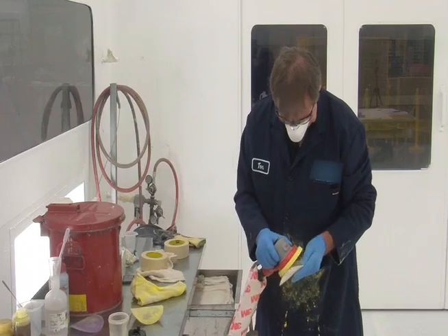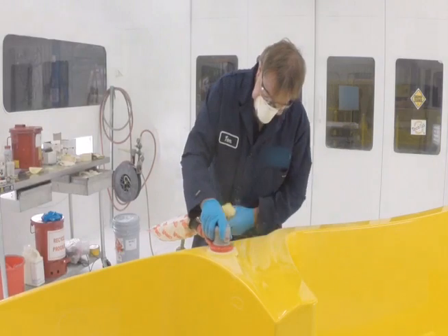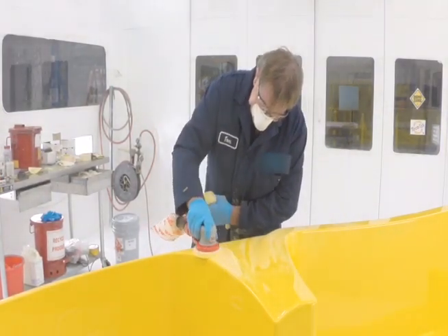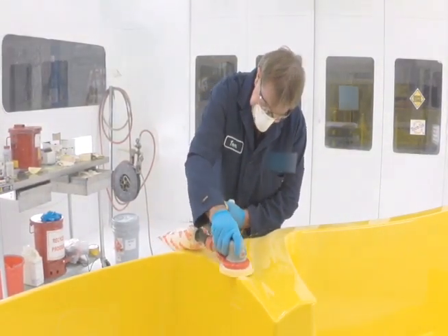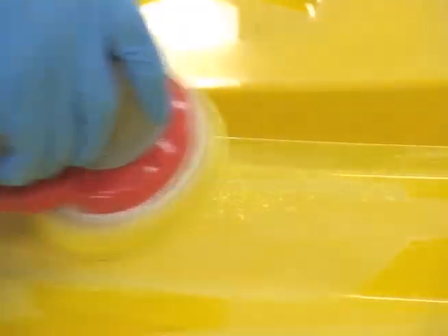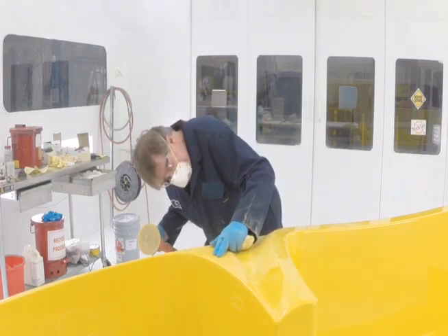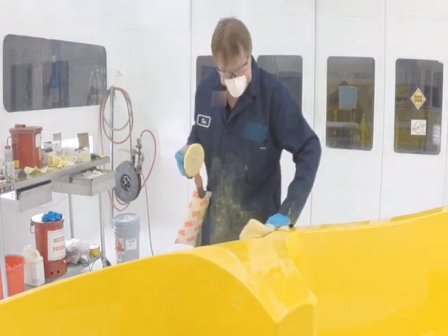The final sandpaper grit should make the patch flash to the part and remove scratches from the previous grit of sandpaper. A finer grit such as 1200 may also be used if desired and may reduce buffing time. Some buffing systems can reportedly remove 600 grit sanding scratches. If the patch shrinks so that the surface is not level with the adjoining areas, repeat the preparation and application steps.